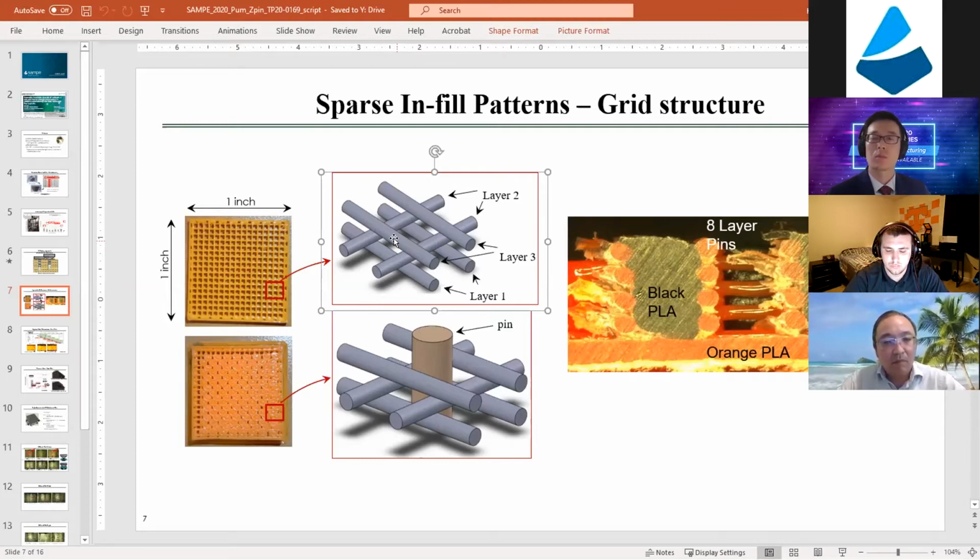The benefit of the Z-pinning we proposed is that we don't need any additional equipment or device to strengthen the Z directional strength. But if there's no hole and we deposit material on the side surface, then it should have been printed with the robotic arm system from the beginning.